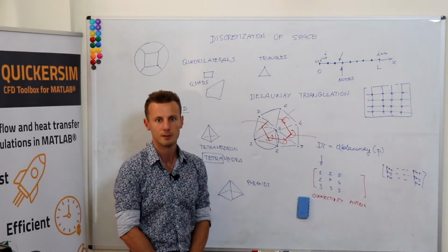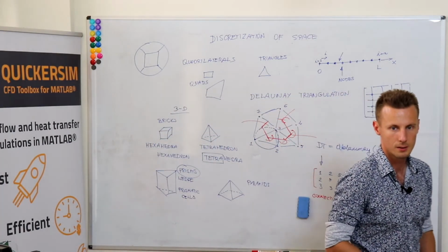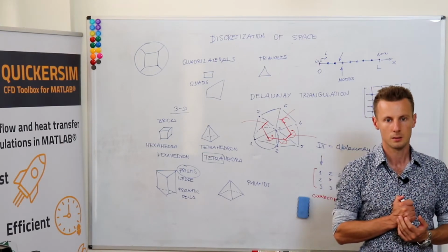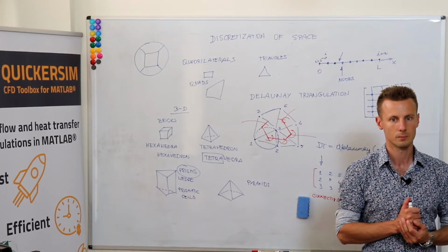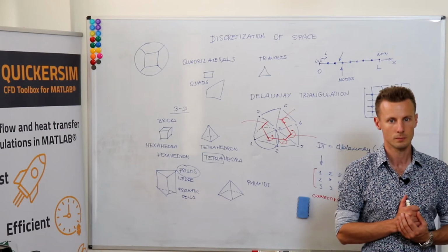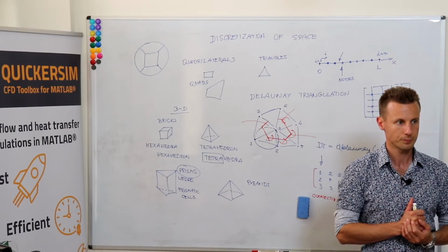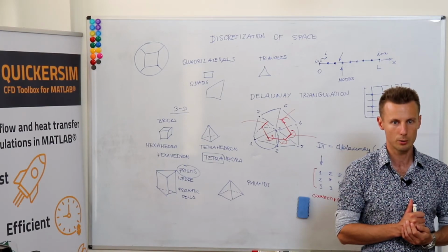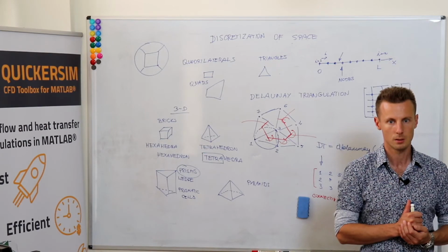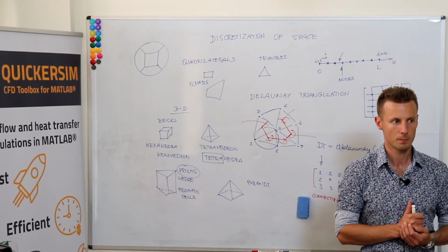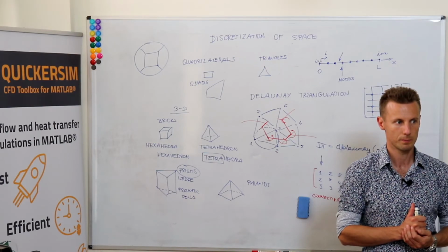That's it. Okay, questions. Why does Fluent, for example, in a cylindrical pipe, use hexahedra by default? Why would you like to use it? No, I did it yesterday for a cylindrical pipe, and Fluent used hexahedra by default. But are you sure you're using the correct phrase, by default? I mean, it may be the default setting in the graphical user interface.